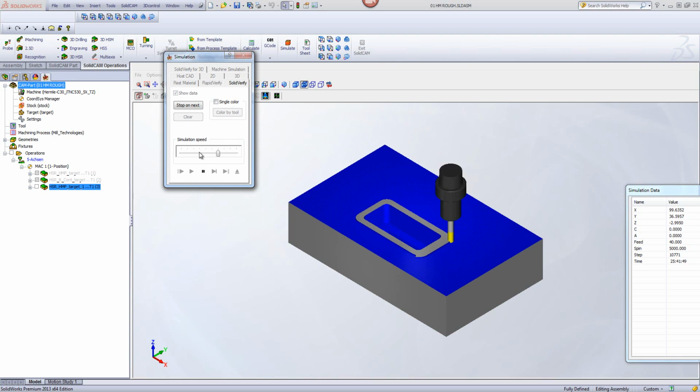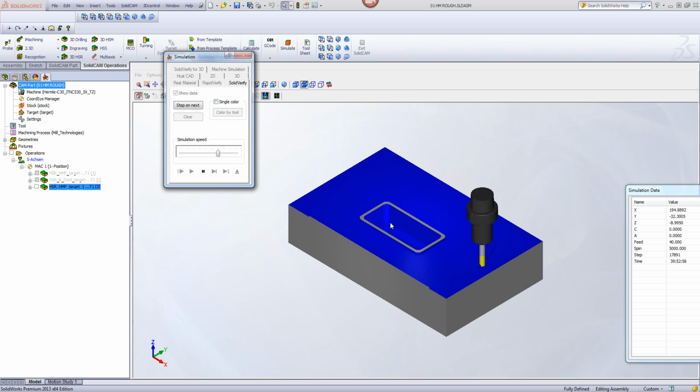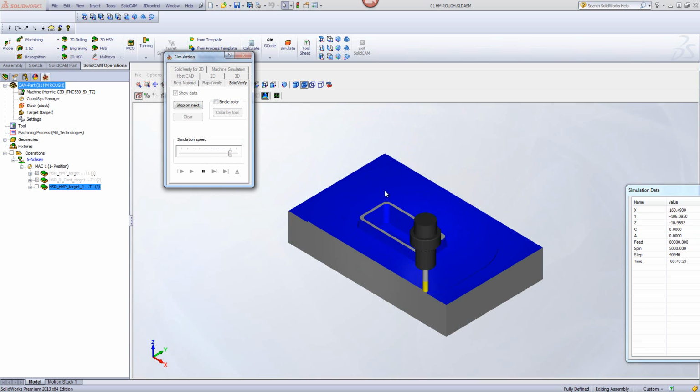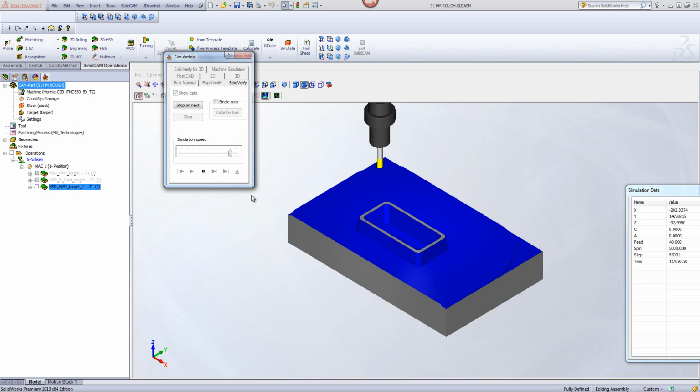When it finishes that, note it starts from the outside, and it actually first cleans off the corners. Let me go a little slower. You'll see it's cleaning off the corners, and then works its way spiral around that area itself. And then this goes down all the way up until which point? Up until the point where we had that little sort of C-shaped area, that little semi-open pocket, and we'll see that in a minute.